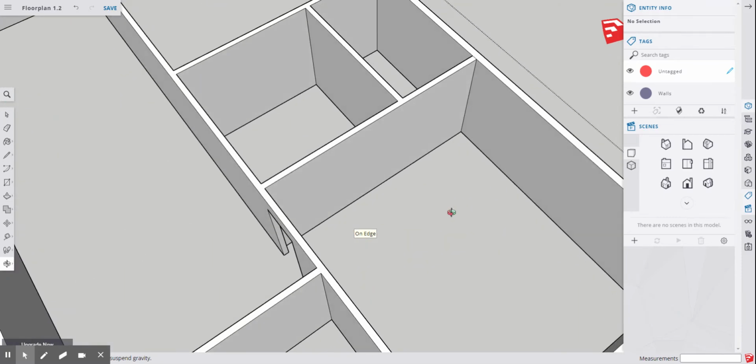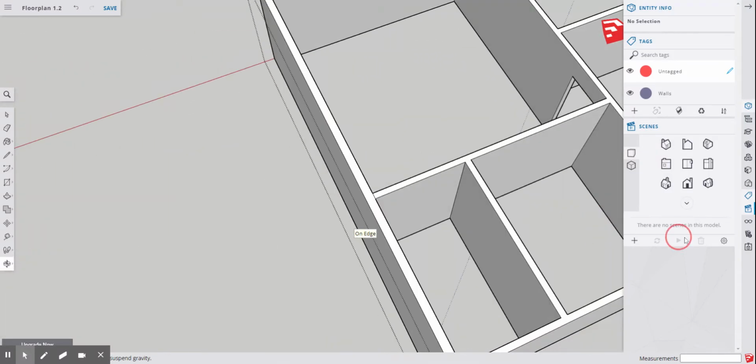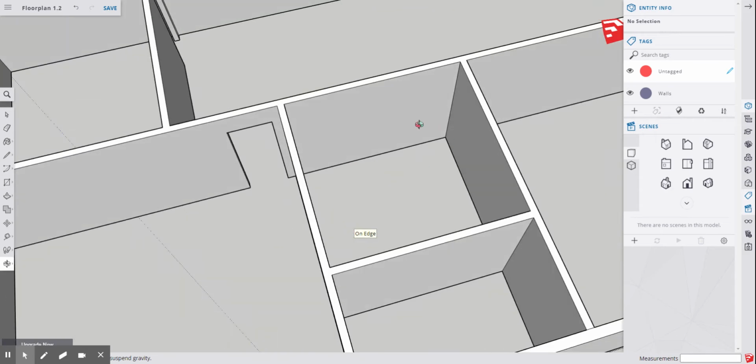Okay, now moving forward with the door into the toilet area, the bathroom. I made mine 6 inches from this point, and we're going to go 6 inches, enter, find it, go up 6 feet, 8 inches, over on the green axis, 2 feet, 6 inches, go down on the blue axis.